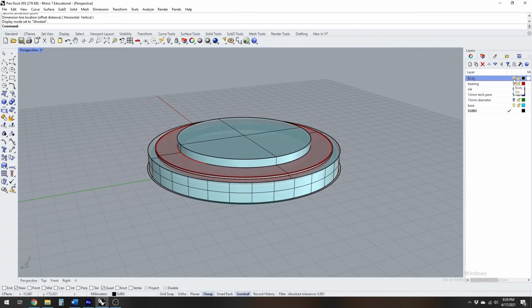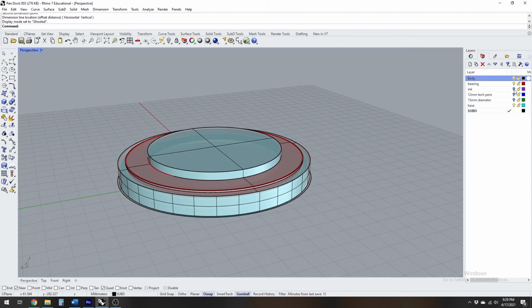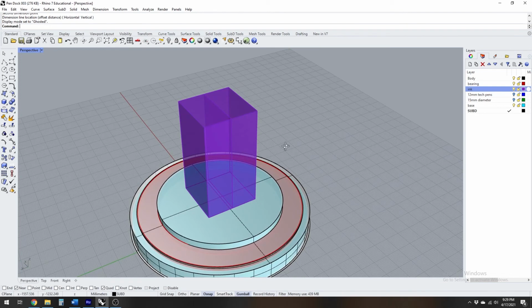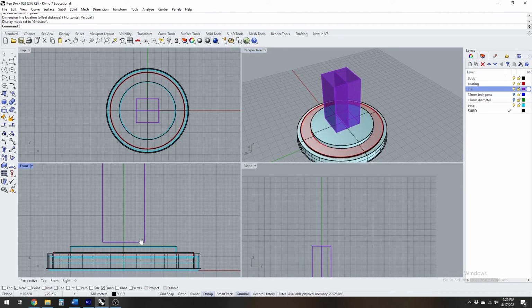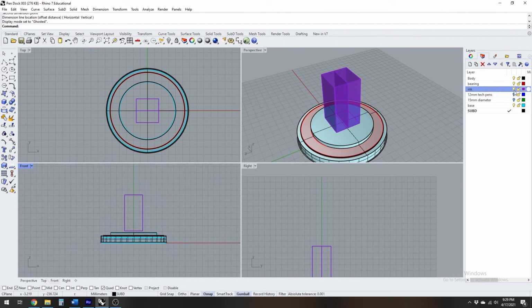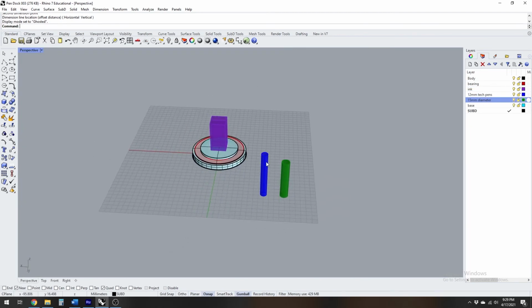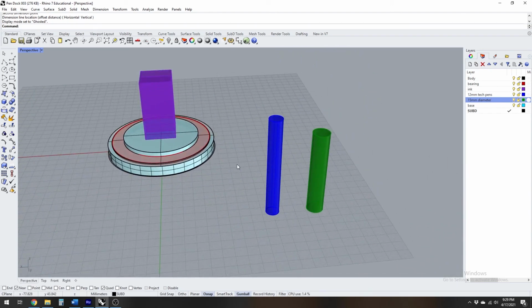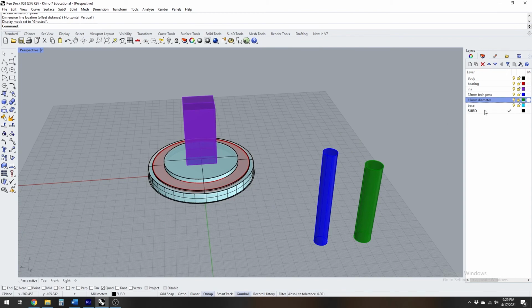The focus of the day is going to be the development of a different surface. Now it does have to integrate with NURBS surfaces, and you can see these purple elements here are two ink bottles that I want to store in the center. I'm just blocking out the basic necessary areas that I need to address. I also want to hold several different diameters of pen, so I have those spec'd out at 12 and 15 millimeters. I will use those later, once we've created our surface, to create some pockets and spaces for the pens to exist within that structure and that base.